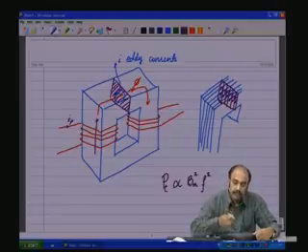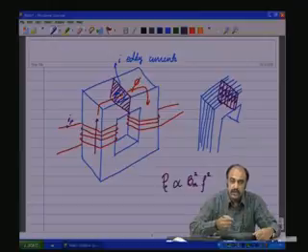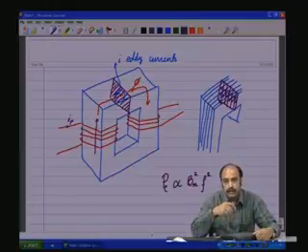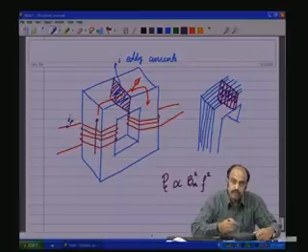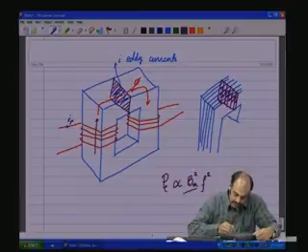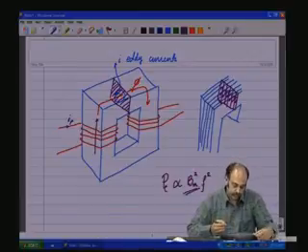Therefore, I induced will also be proportional to the amplitude of the flux density, and the loss is proportional to I square, or Bm square. Hence the term square of Bm.